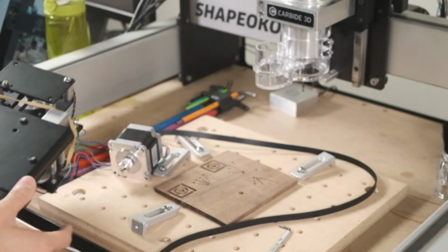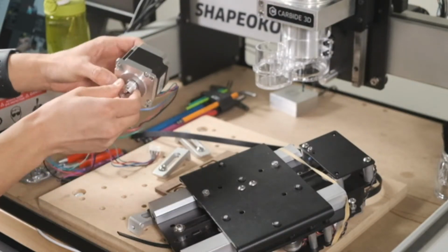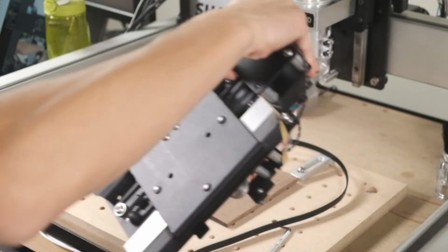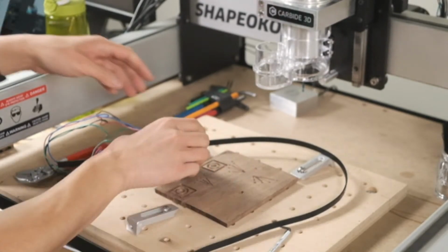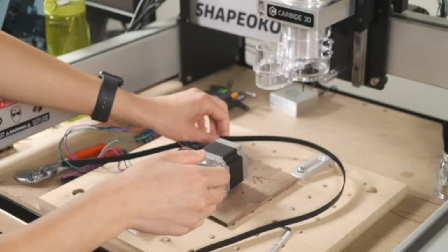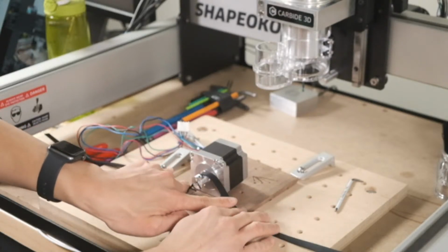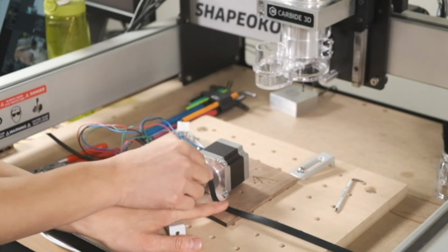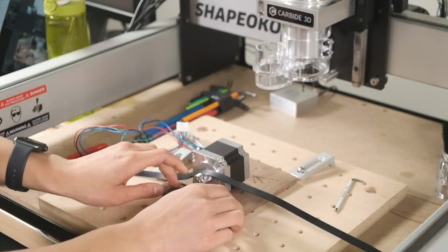Now, in addition to just the pulley itself being tight, you can also have the belt being a little too loose. So it's getting a little too cluttered. If your stepper motor has a belt just very loosely draped over it, there's no guarantee that the pulley teeth are actually going to engage this, or they might slip or jump. So make sure your belts are tight.